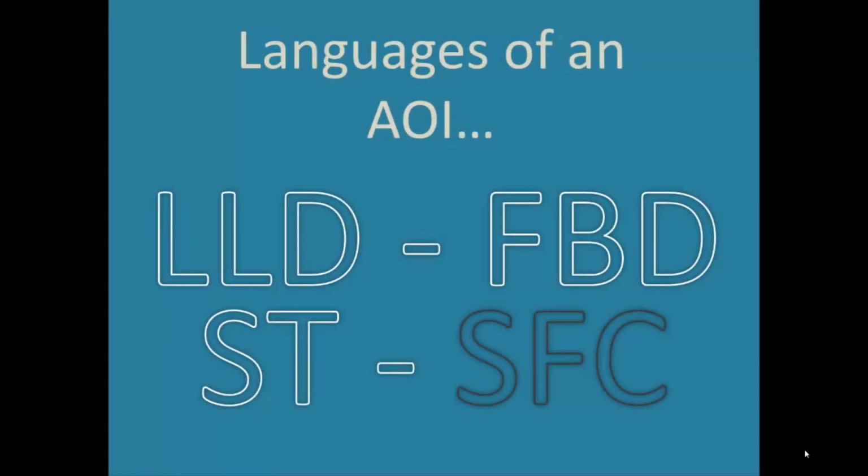Programming languages for add-on instructions. Select the programming language based on the type of application you are developing. The rules are the same that you would use for selecting the language for a subroutine. Each of the languages has a very specific advantage in certain applications. So you can pick ladder logic diagrams, function block diagrams, or structured text. Sequential function charts you cannot use inside of an add-on instruction.